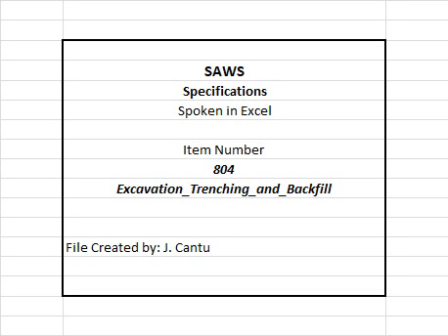All compaction within the secondary backfill zone shall be such that the relative dry density of each layer shall be not less than 98% compaction from the top of the initial backfill to the bottom of pavement section as outlined in TXDOT testing methods TEX 113 or TEX 114. For native sand backfill and non-cohesive soils, engineer will specify compaction requirements. The second lift shall be evenly spread in a similar manner as the first lift.